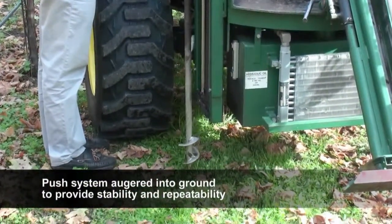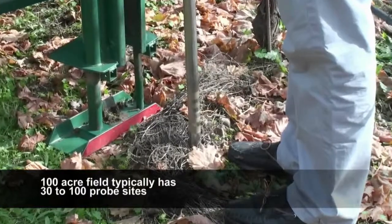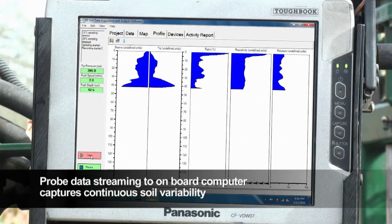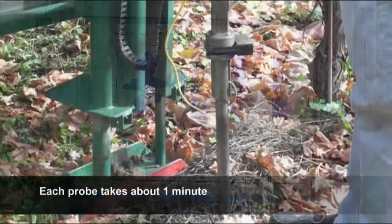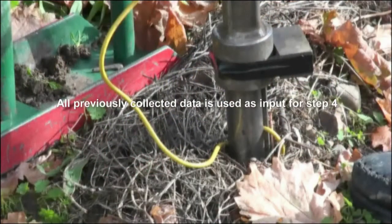The geophysical probe is pushed into the ground to collect continuous data streams for tip force, sleeve friction, moisture, and electrical resistance. Monitoring data signatures using the onboard computer while the data is being collected helps STI ensure data quality. The entire process takes approximately 5 minutes to collect data at each location.